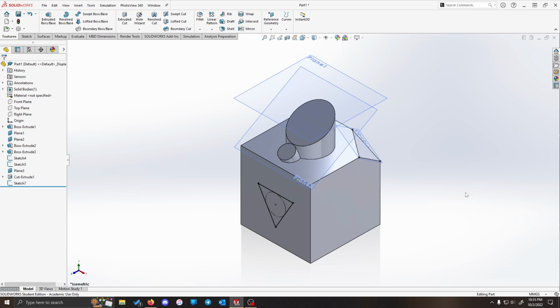This makes coordinate systems very powerful tools with a lot of options and use cases. But we're going to focus on one of the simpler applications for now. On occasion, you'll want to be able to set up a plane that is both offset from a given point and set at some angle from a given surface. With standard reference planes, you'll often need to chain multiple planes and/or create sketches to define offsets and axes of rotation. However, with a coordinate system, we can do both of these simultaneously.